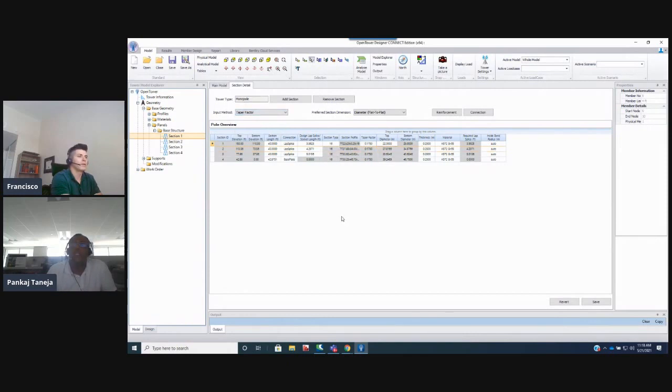That taper factor means that, hey, you define the section length, you tell me the section type, how many it is, 16, 16, 18, or whatever it is. You tell me the top diameter and taper factor. Let me calculate the bottom diameter of the rest of the tower for each section. Got it. So it saves a lot of time for the user instead of going back and doing the maths by hand, because engineers' time is precious, right?